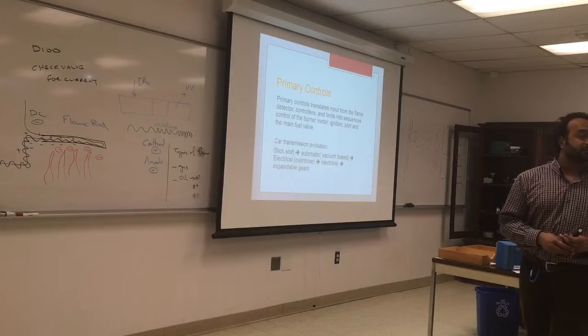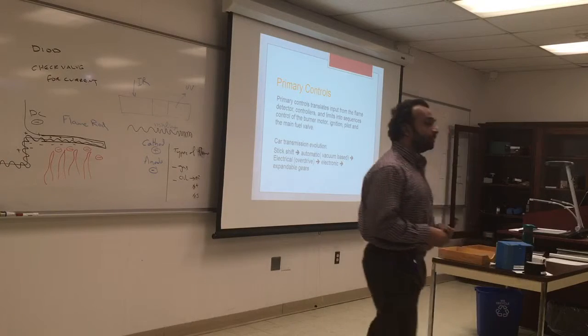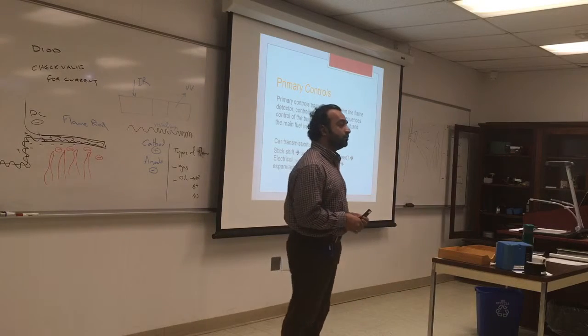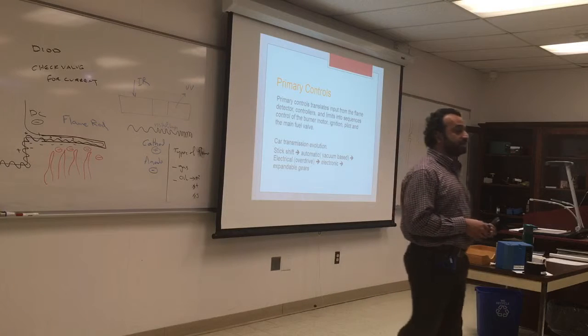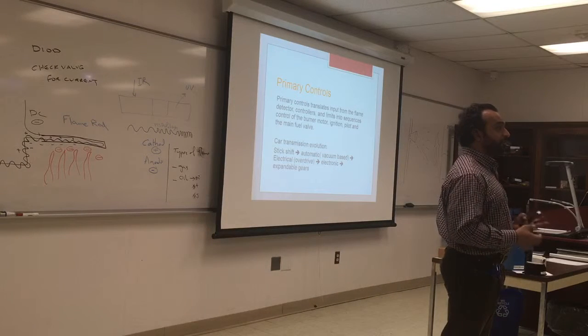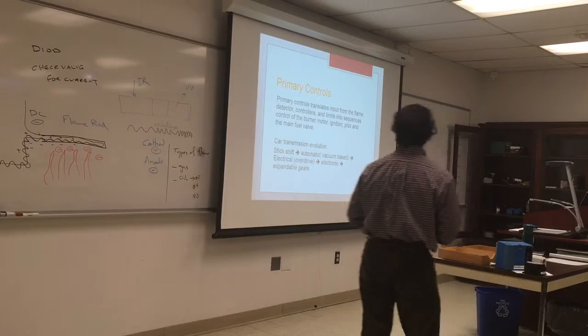Why is that? Because you don't want to turn on the main flame when there is no sure source of ignition. And the amount of fuel that is injected into the boiler is huge, so you don't want to risk that.